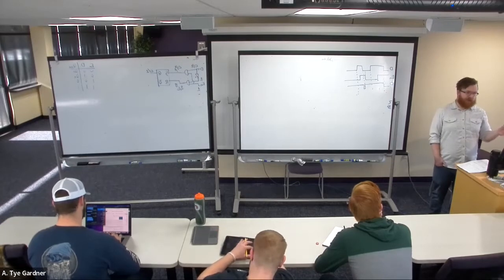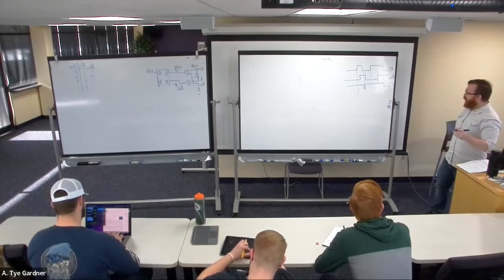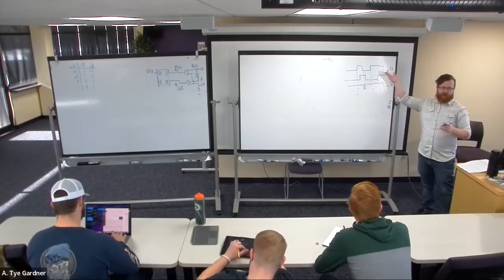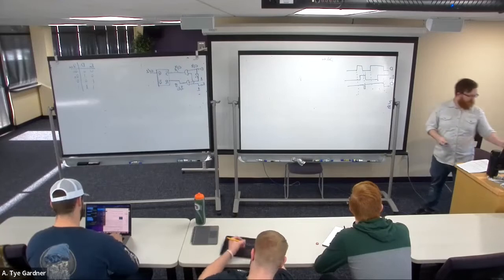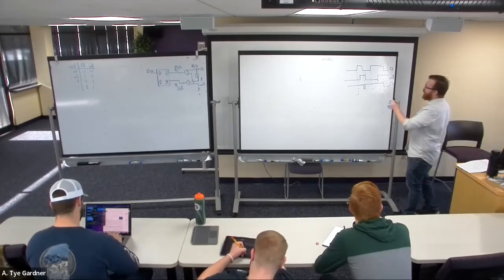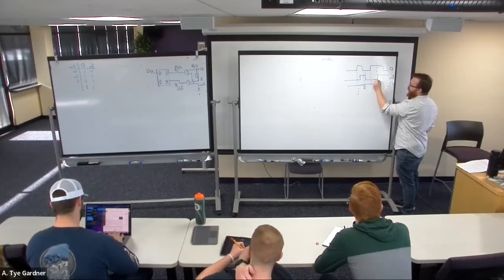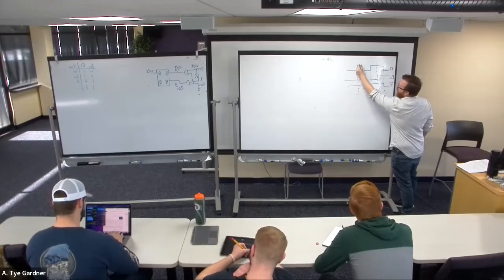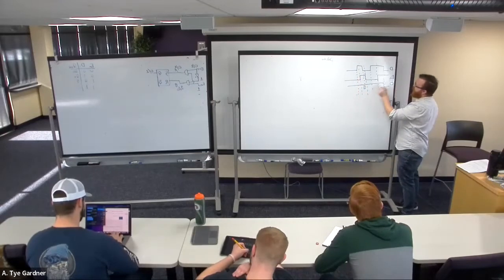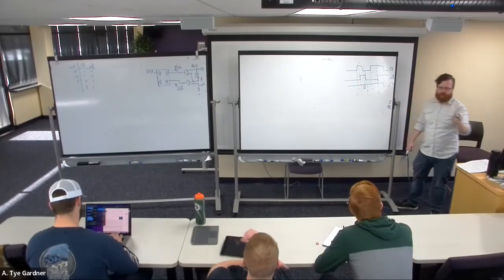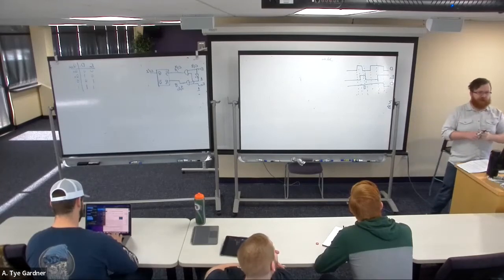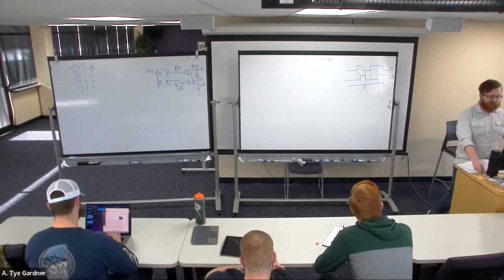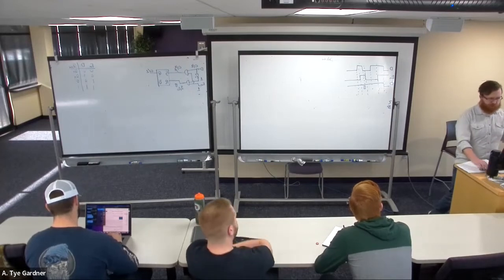So what you want to do in a timing diagram like this is go identify the locations where something changes. And it would be really good if I had the full swath of colors, right? Because then I could be like, well, here's another interesting point. That's an interesting point. And that's an interesting point. And now I have the blues, which is where D changes, and the greens, which is where enable changes. And those are the only places where Q is going to change. And in fact, Q is only going to change if enable is true.